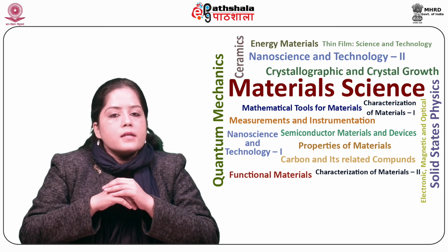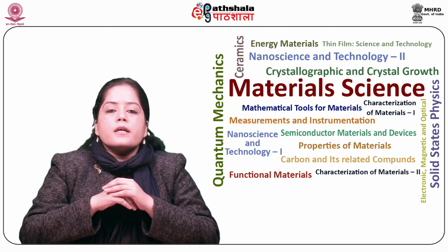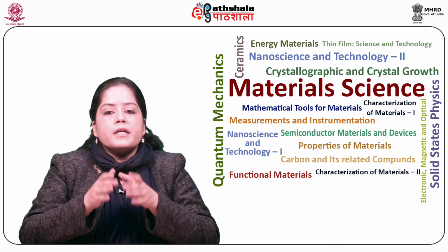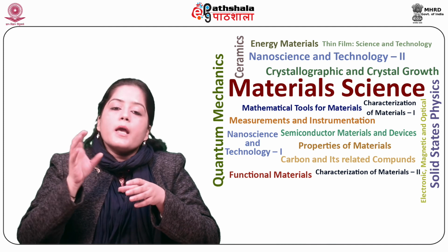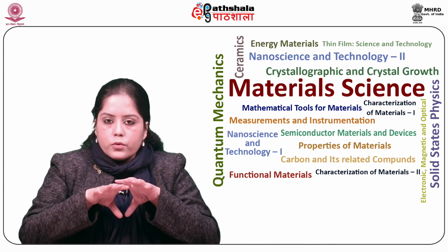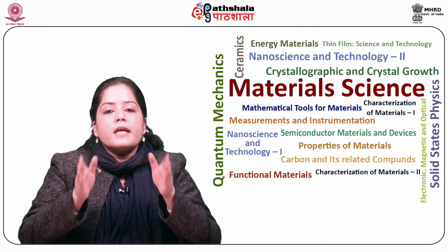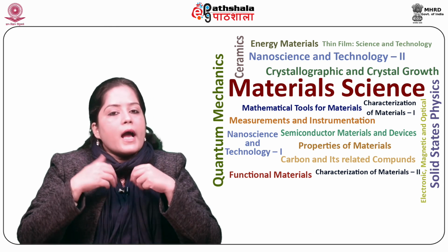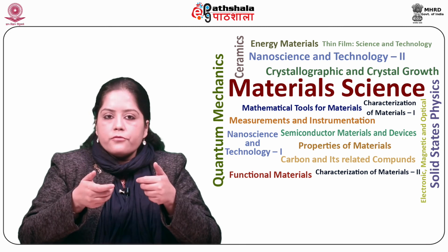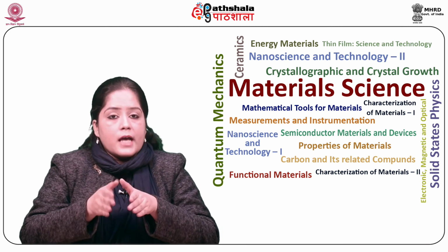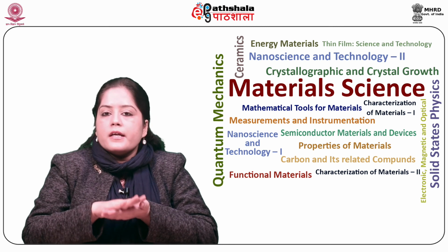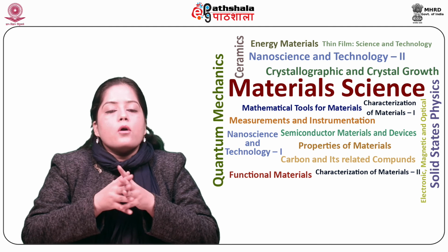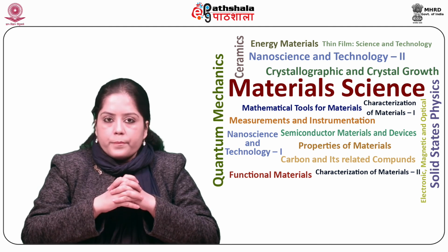You make a master stamp using high resolution techniques like electron beam lithography and apply the stamp onto a substrate for creating the desired pattern. Additionally, for making thin films in the pattern of the stamp, a very thin layer of the material or the ink is deposited on the surface of the stamp.